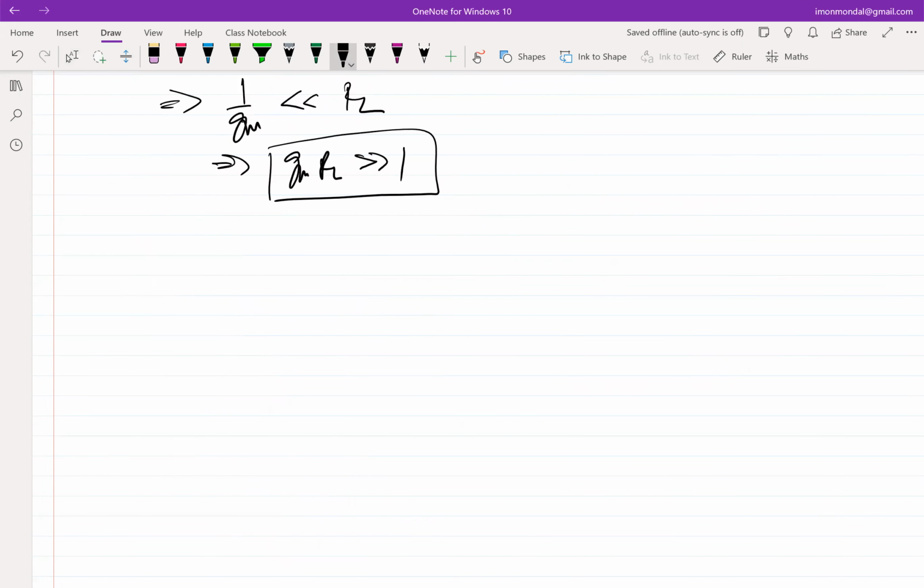So before we move on from this particular configuration, there is one last point that I would like to make, in the incremental sense. If you recall the way we came up with the same network in two ways. One was while we are trying to bias our network by adding a constant current source at the source, and also while we are trying to get a voltage buffer kind of thing, right? Where we are trying to get an output which tracks the input.